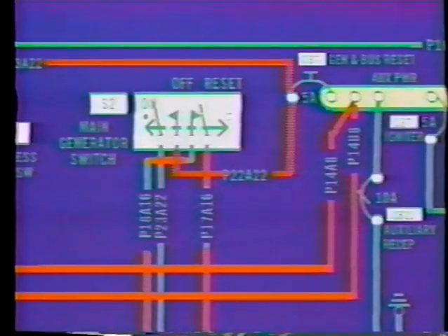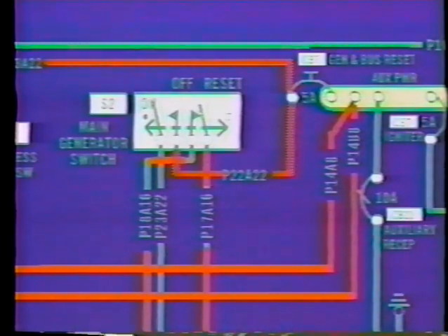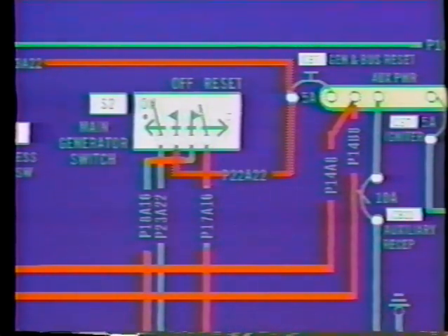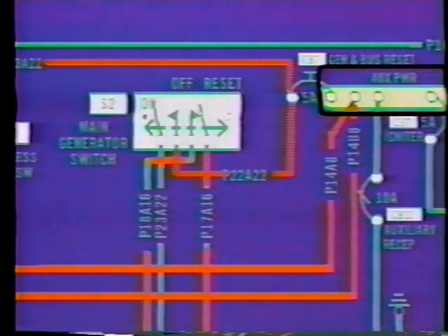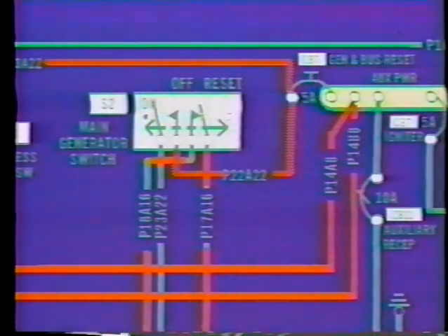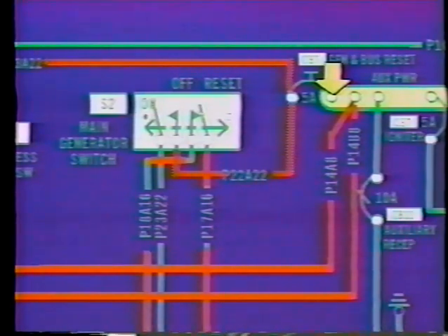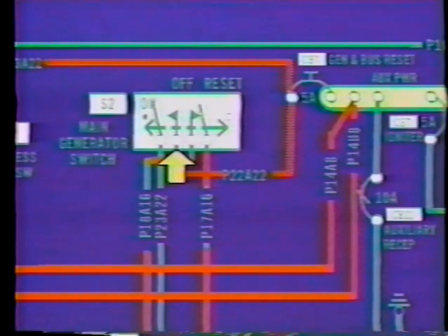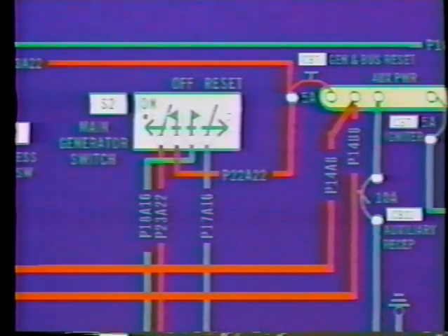When the generator comes offline, battery power will still exist on the bus. To begin the field flashing trace, find the overhead console essential bus. On this bus, find the generator and bus reset circuit breaker. Go through this breaker to the generator switch. Move the switch to the reset position. This will displace both the flippers within the switch to its opposite-most position.